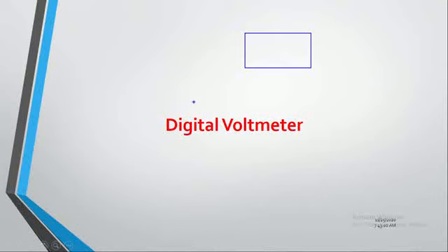But how exactly is this digital voltmeter measuring the voltage of the input signal? For that, we take two inputs to one block, meaning this digital voltmeter is taking two inputs. One input is a known signal, meaning we know the voltage of this signal. I'm assuming that this is input 1. So to input 1 of the digital voltmeter, I'm taking the known signal. To input 2, I'm applying the unknown signal.